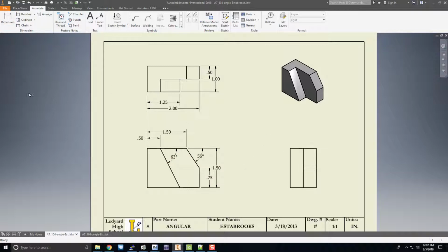Now, we're not done yet, because as soon as I put in those angular dimensions, two of my coordinate dimensions become redundant. In particular, this dimension right here. So imagine this. We know this distance from this point to this point. Since we also know this angle, this point down here must go to that point. We don't need that dimension anymore.